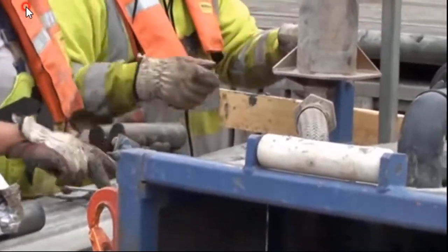Here, and the last one is the rotary samplers. Rotary samplers are used for stiff clays or rocks to collect rock and soil samples, because when the soil is very stiff and very hard, the sampler will not penetrate easily. Then you need to rotate the sampler and send it inside. Therefore we have rotary samplers. Some examples are shown in the figure.